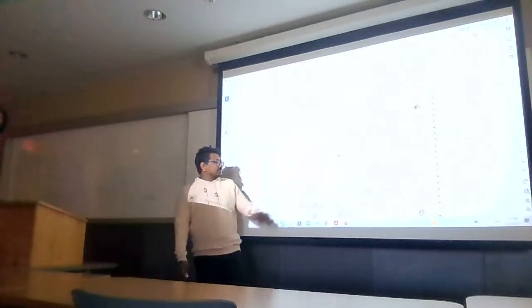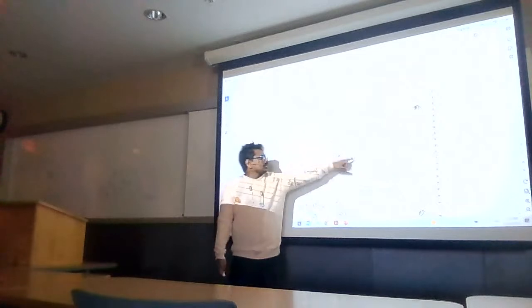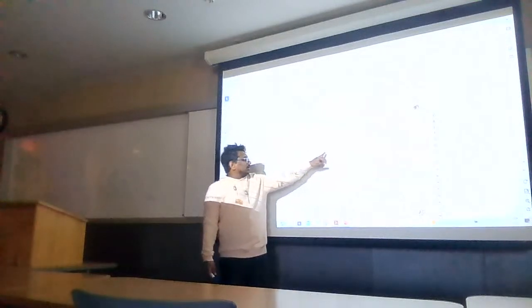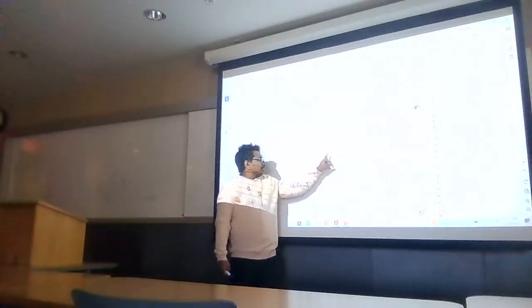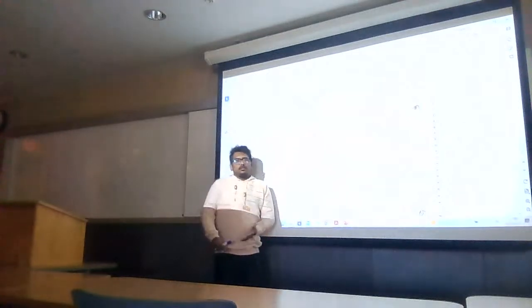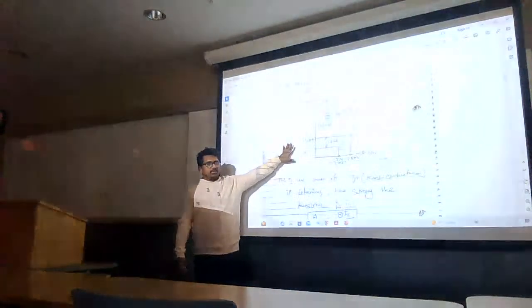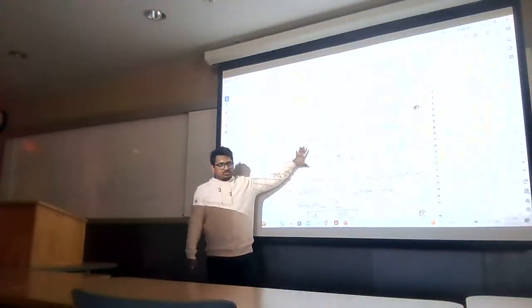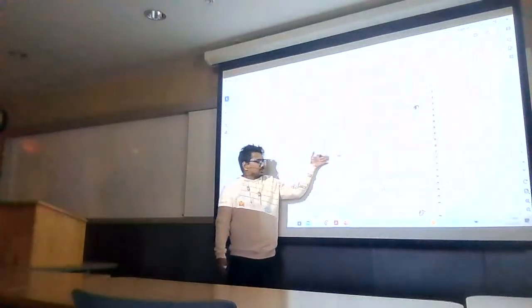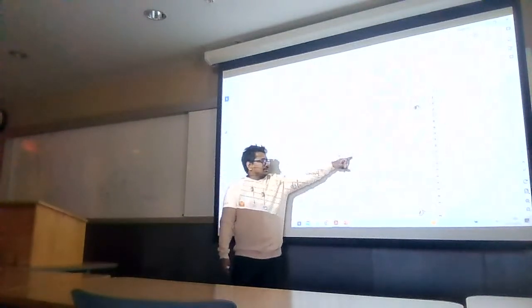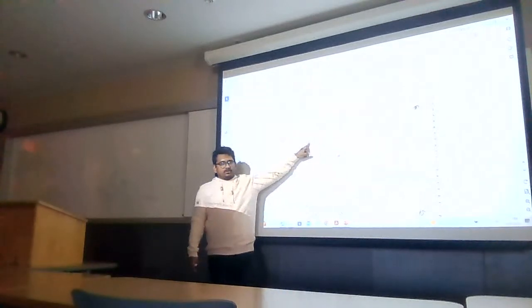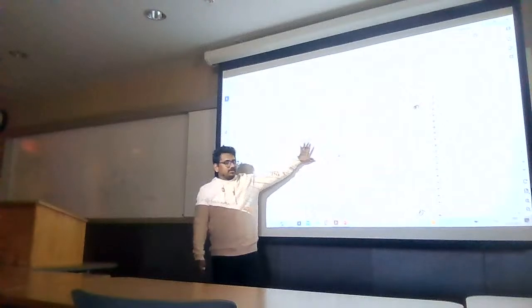If we fix VDS and play with the VGS in the saturation condition, then we will find a curve like this. And this curve says that I can expect, whenever I express some formula, you can see that if my ID, drain current, is huge, then my transistor is strong. It can produce more gain. So I need to push my circuit in this way, to this point as much as possible, because you can see it can provide more current there. This is the significance of this curve.